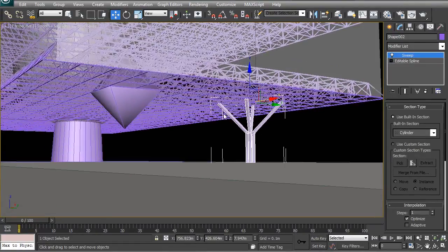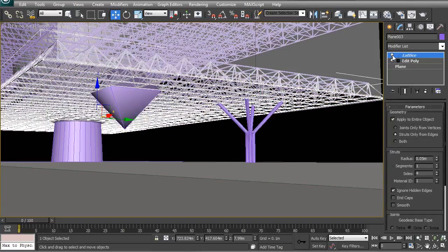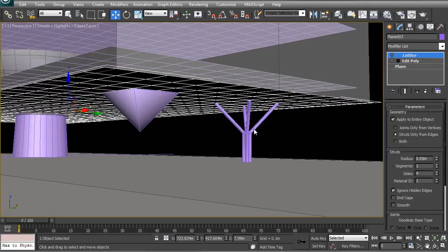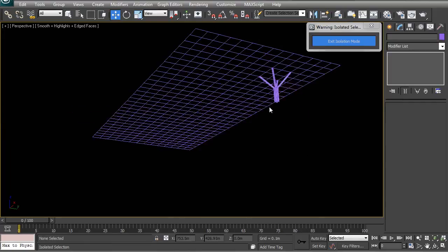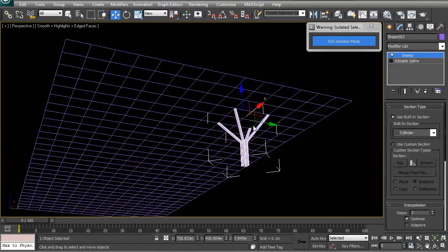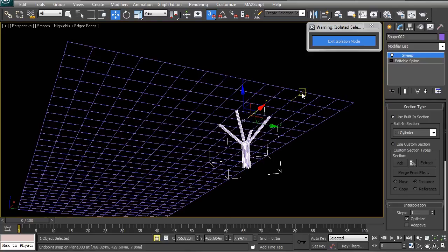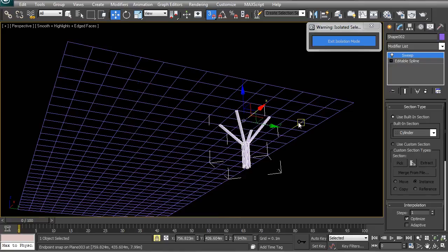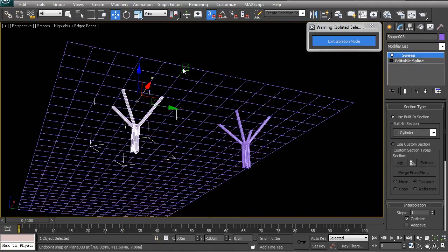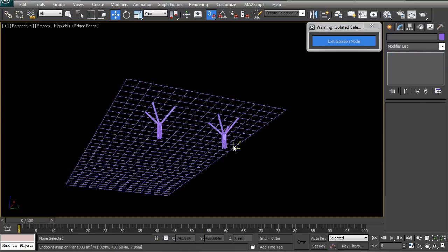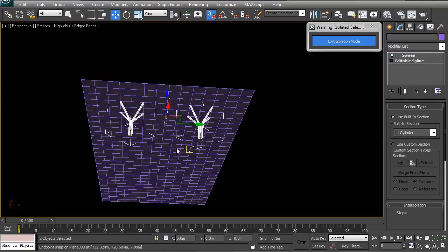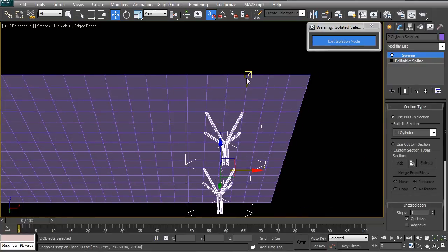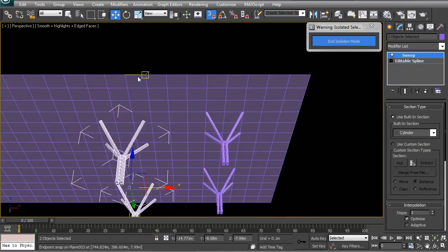If you want to be quite precise, you can take the structural lattice and, removing the modifiers, you can see how you can use a common point to copy it. If I just select my object, turn on your snaps, turn on your lock selection, you can use an existing point and copy it in that way. Just holding down Shift will allow you to create an instance having a common point between the objects. The same thing can now be done in this direction, where we can choose to copy it like so.